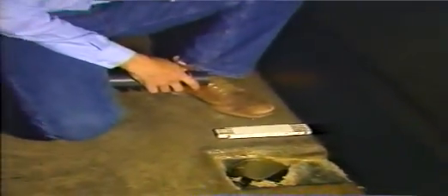Finally, whenever you're in the interior galleries of a concrete dam, check the foundation drains. These drains help relieve uplift pressure beneath the dam. Sometimes drains become clogged with chemical deposits. Clogging reduces flow and causes dangerous uplift pressures that potentially can affect the stability of the dam. Note the location of any drains you suspect may be clogged.